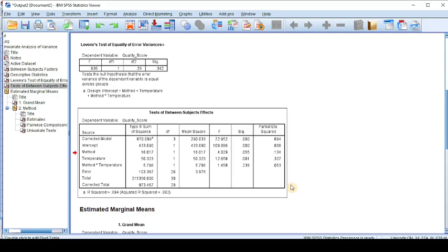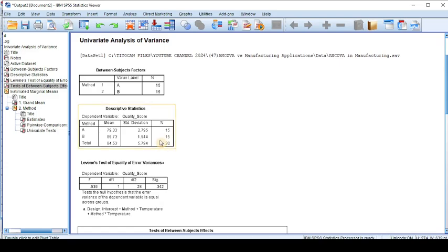But if the analysis had shown a significant difference between the methods, the manufacturing company would have confidently selected the method that produces higher quality scores adjusted for temperature, leading to more consistent product quality and potentially lower production costs over time. This is how to apply ANCOVA analysis to decision-making in the manufacturing industries for best quality scores, and I hope you'll be able to replicate these procedures.